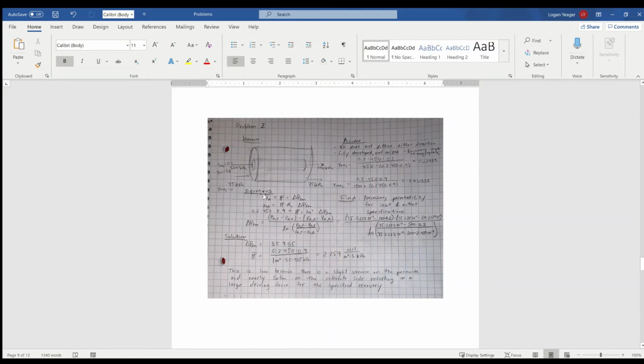And so using that, we can find the total molar flow rate, and using this expression, we know the surface area, and we can calculate the delta P log mean of the partial pressure of the ammonia. We plug it into this equation, which is the total molar flow rate divided by the surface area times the delta P log mean, and we get a necessary permeance of 2.254 moles per meter squared seconds kPa. And this is relatively low because there's such a high pressure on the inside and such a low pressure on the permeate side.